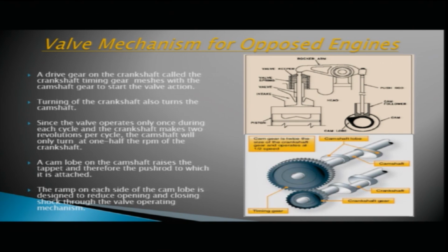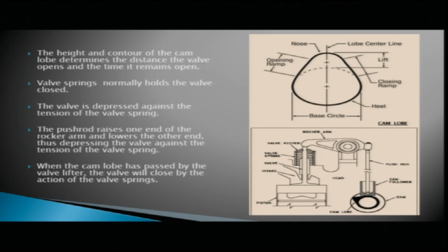The ramp on each side of the cam lobe is designed to reduce opening and closing shock through the valve operating mechanism. So the design of the cam lobe is such that it reduces opening and closing shock through the valve operating mechanism. The height and contour of the cam lobe,